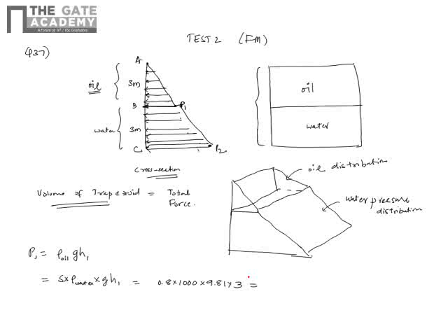So let's calculate this pressure. This value comes out close to 23,544 pascals pressure at P1. Now pressure at P2 will be your pressure at P1 plus the pressure produced by the weight of the water column, so that is rho g H2. So pressure is 23,544 plus water 1000, density 9.81 into 3. So this pressure comes out close to the total value 52,974 pascals. Okay, so you have the individual pressures.